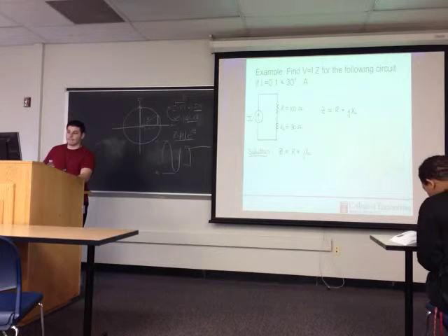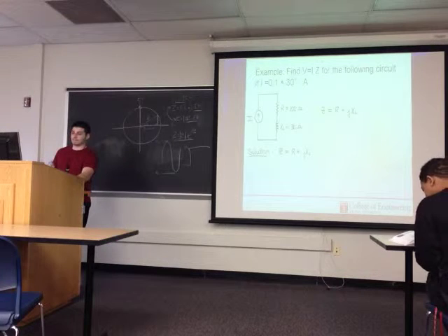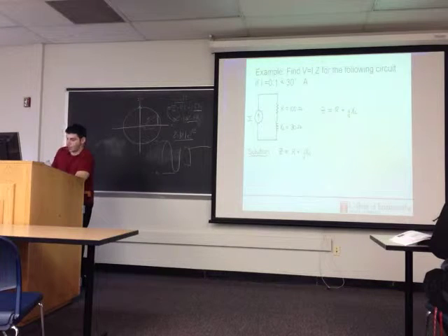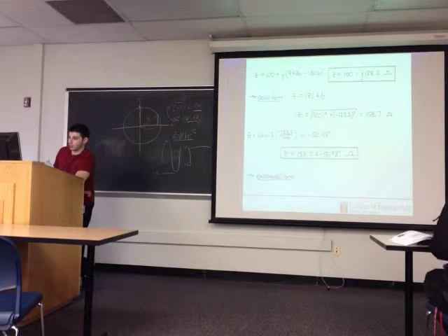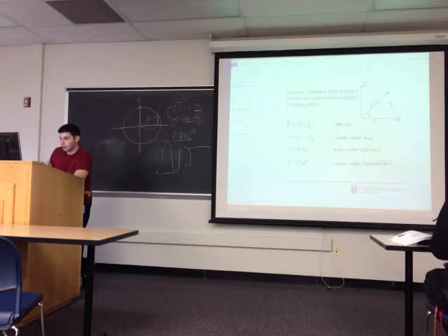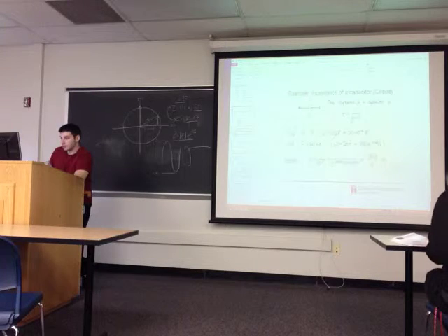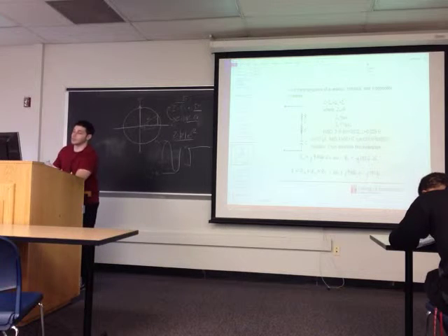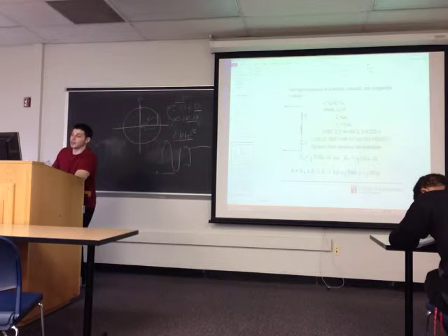So how come in the last problem you added them all? We didn't have them as separate entities. Well, we did. If we go back, for this one right here, we added all of the impedances together. But we know that Z of L is imaginary and Z of C is imaginary, so we added the imaginary parts and left the resistance as is, which is just real.